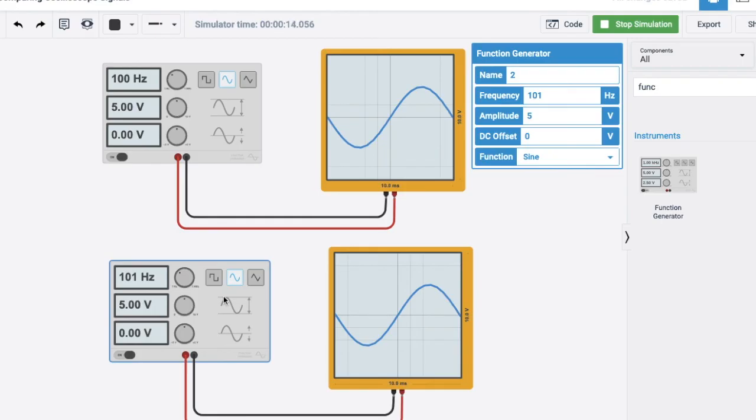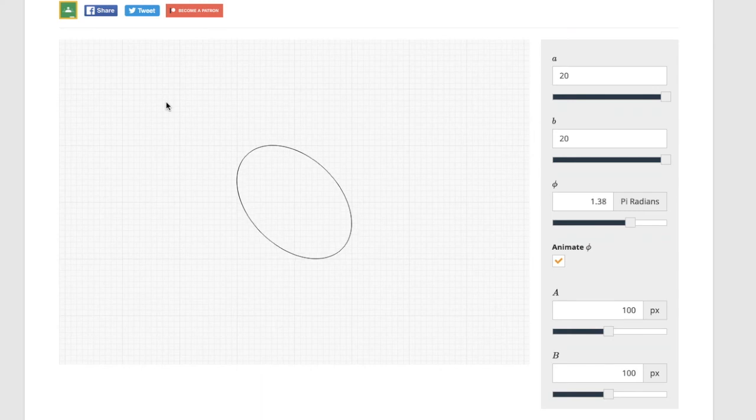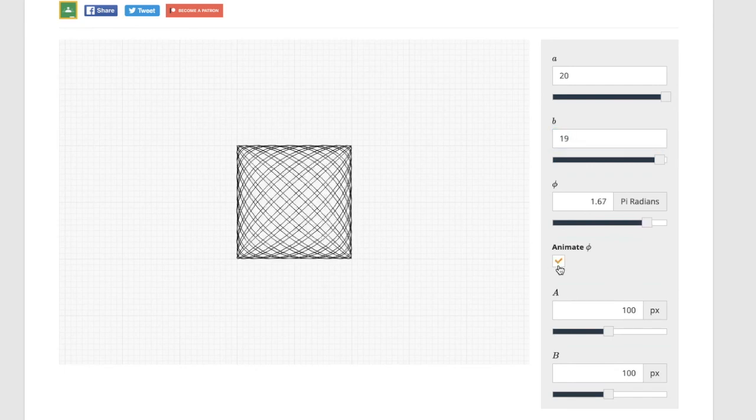Unfortunately, I cannot oscillate one signal along the vertical axis because this is just a simulation, but in many oscilloscopes, you could actually transfer the oscillation of one signal to the vertical axis and not just along the horizontal axis, and you will be able to observe the Lissajous curve. And the Lissajous curve actually tells you that if two signals are equal, meaning they have equal amplitude and frequency, regardless of the phase difference between them, they must be displaying a slanted circle that rotates along the vertical axis. Otherwise, if there's some small differences between the frequencies of one signal, there will be a change in the Lissajous curve or Lissajous pattern.